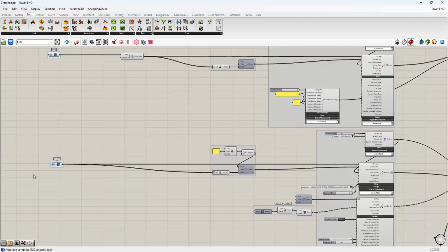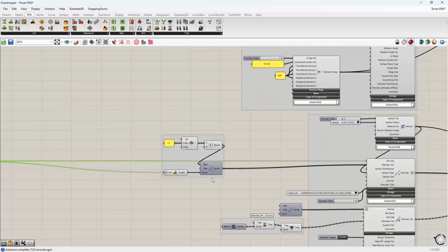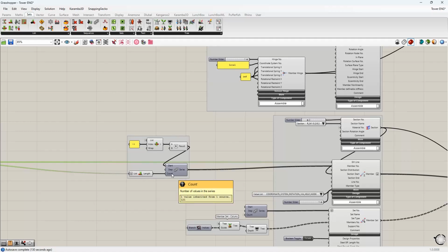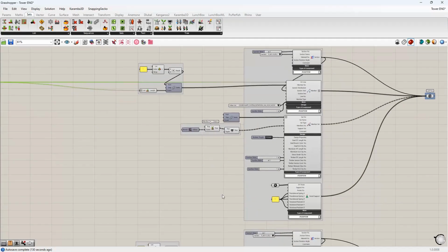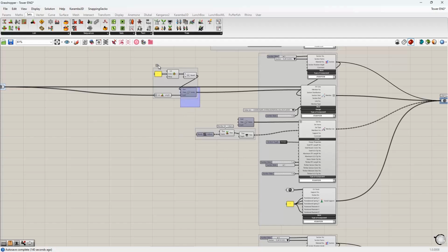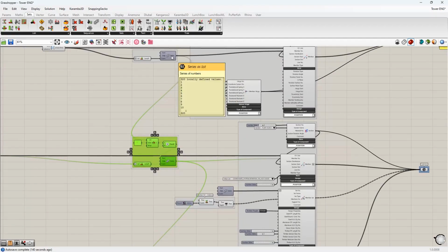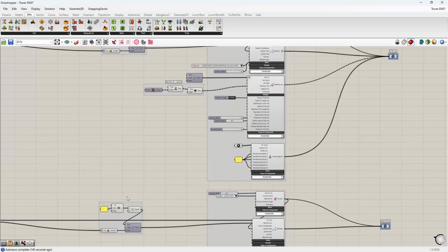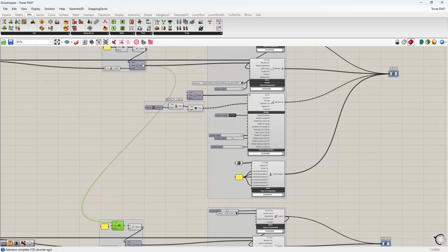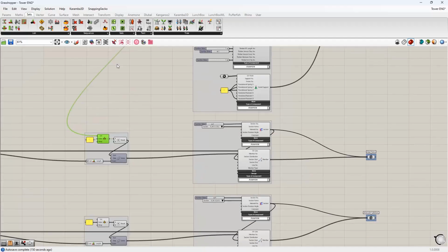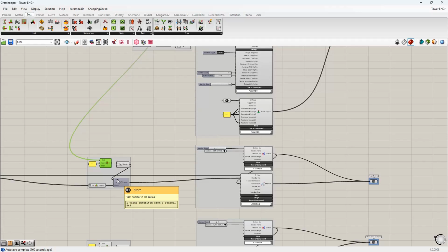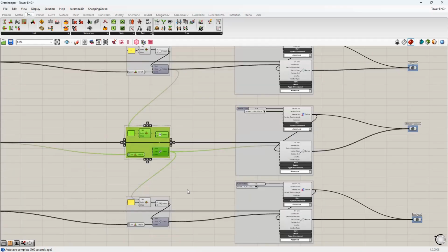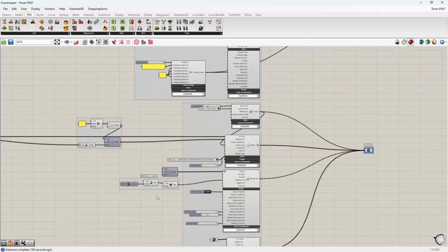Step also 1, and the count again is the next list, that's our column list. And we have now the series for our column members. If you generate further members, like here, it's just a copy and paste function. So you continue the series of this component, and here the numbering is continued with this series. Here it ends at 441, and this starts at 432, and so on. So it's very easy to keep track of the numbering.